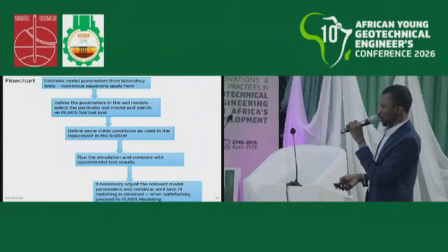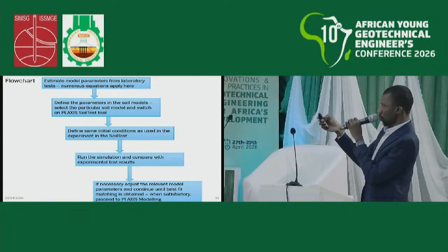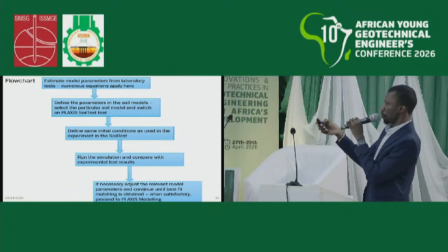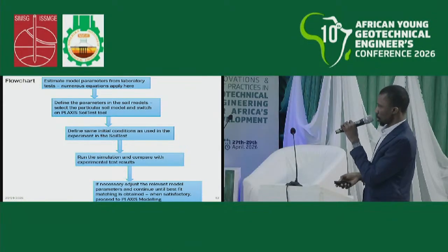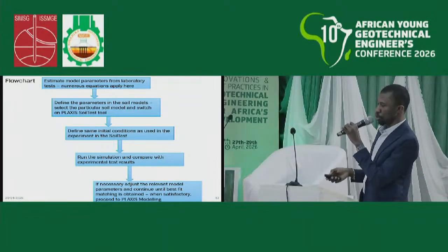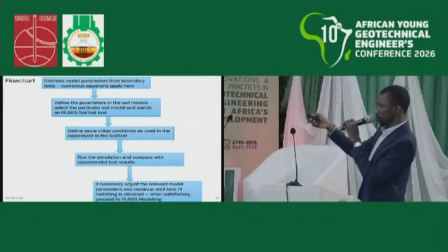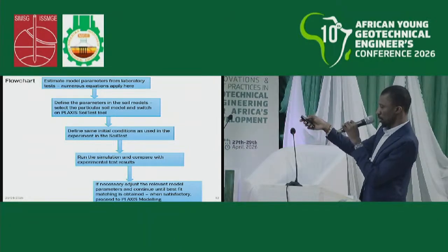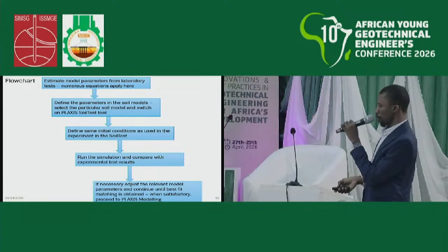And this is an example of a laboratory test. This can be obtained from an oedometer consolidation test or from the consolidation stage in the triaxial test. This is for both the lateritic soil and the saprolitic soil. It was done at different suctions: saturated, 100 kPa and 300 kPa. Then this is the procedure used to obtain the slope of the normal compression line. You fit from where the soil changes direction, which is called the pre-consolidation stress. From that point, you can fit the points, find the baseline, and from there obtain the slope of the normal compression line for each of the soils.